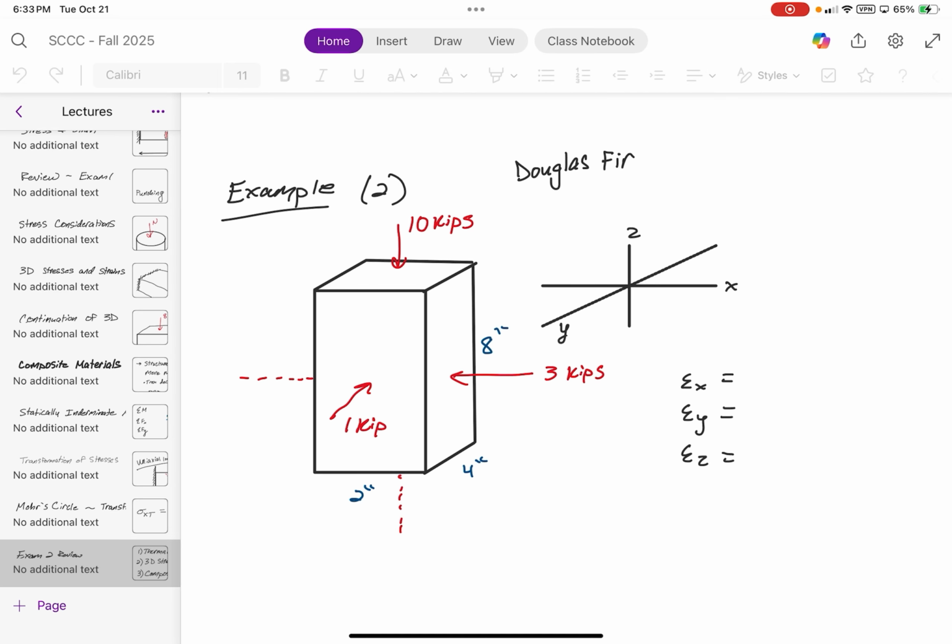So when would you have to use the stress over the elasticity? When would it be appropriate? Only for the normal strain. So if you wanted to find, for example, the strain due to axial loading only... I've got to find a way to explain it. In a case where you have a problem that looks like this, there are going to be lateral strains also, but this would be like sigma z.